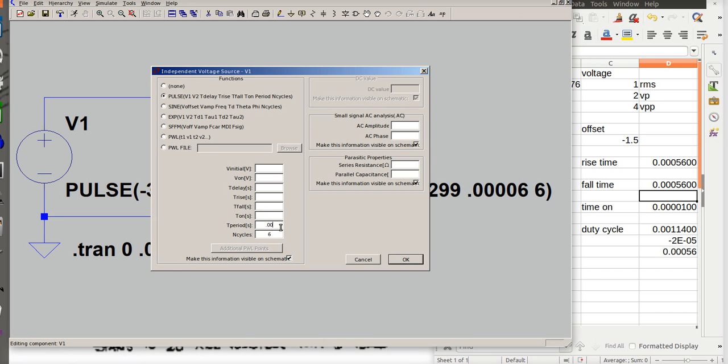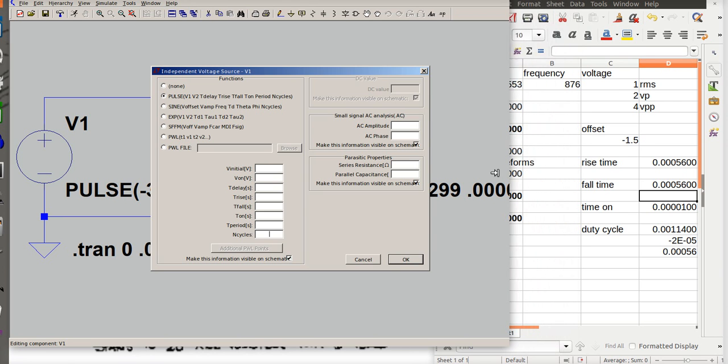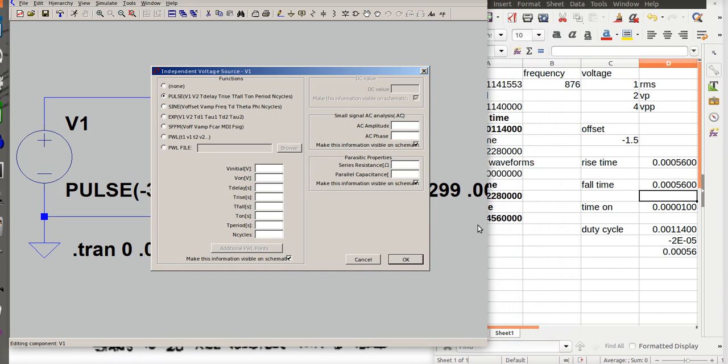And if you get multiple problems on a worksheet, you're going to have to do this. You're going to have to blank it out or go with a new spreadsheet. Maybe I can make that to where I can see everything. That'd be sweet. I'm shortening it, but I can see. Okay, I want an on voltage and my off voltage. So it's going to be offset 1.5, and it's going to be 4 volts peak to peak.